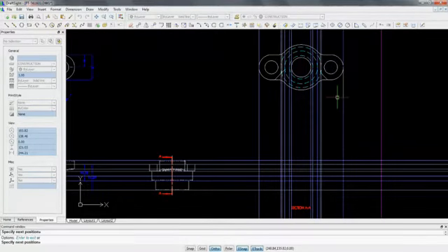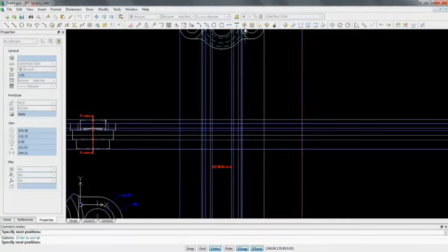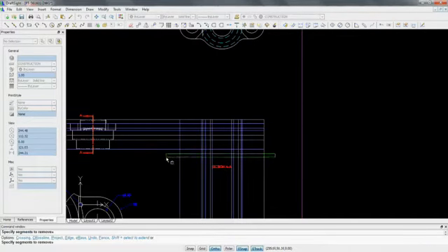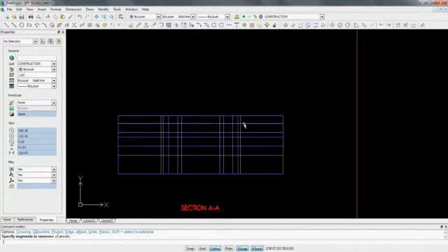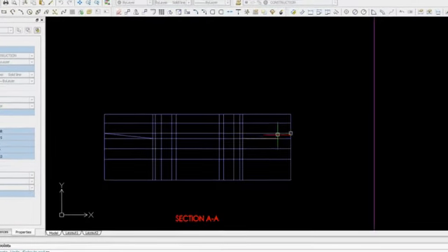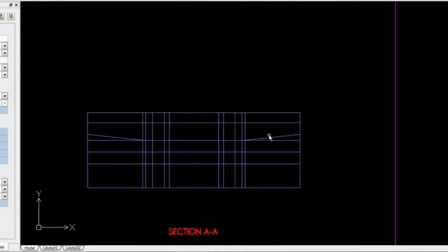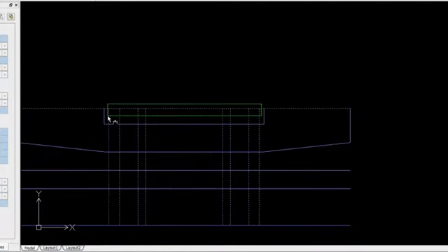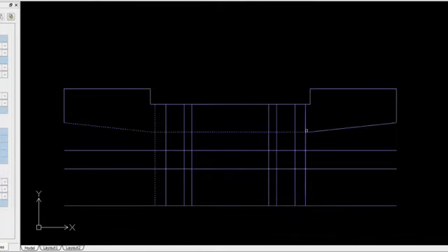In this case, a new section view was needed for an old drawing, and all of the construction lines have been created. Using DraftSight's trim tool, it's pretty straightforward to get to work cleaning this new view up. You select using traditional box select methods and can use these for selecting the items to trim also. You might also notice there's no need to repeatedly press the trim button, as the standard spacebar and enter key to repeat are honored in DraftSight.